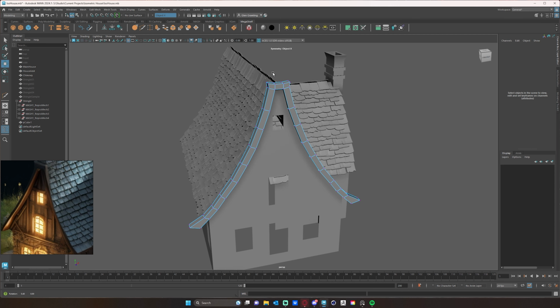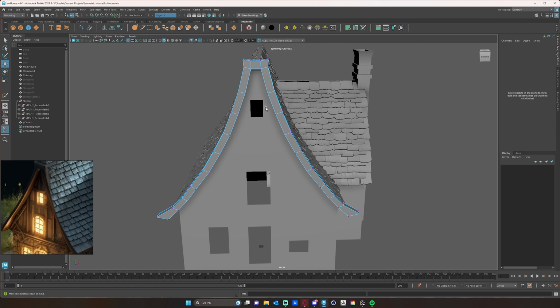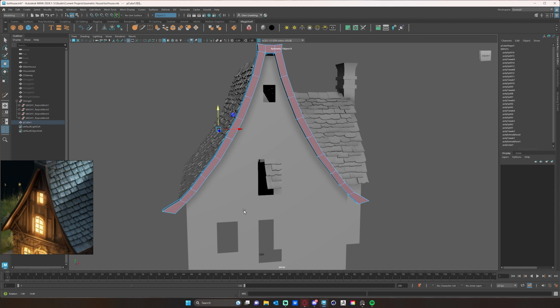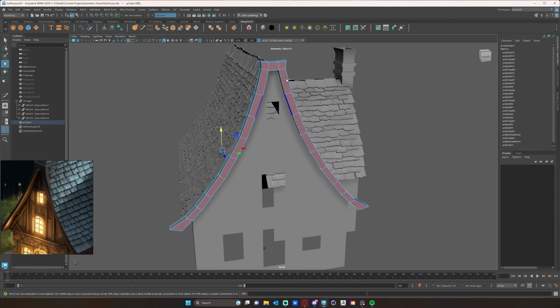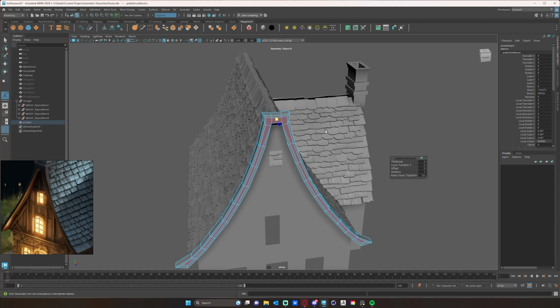So now I think what I'm going to do, just again to add a little bit of extra style and flair to this, I'm going to grab all of these front faces here. So I'm just holding down Shift and selecting all of these front faces. And I'm going to hit my extrude function, and I'm going to extrude them all in a little bit. It may not deform properly. As you can see, it's not really deforming properly up here as I would like.